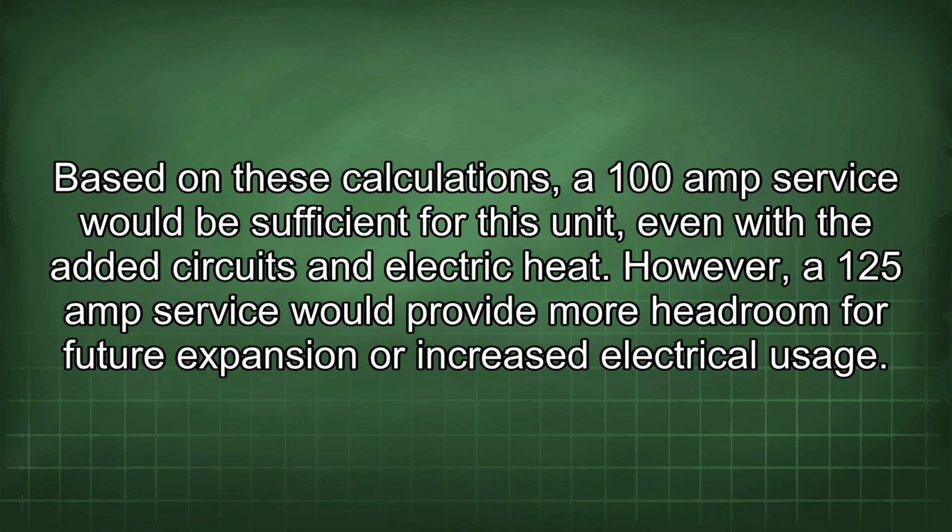Based on these calculations, a 100 amp service would be sufficient for this unit, even with the added circuits and electric heat. However, a 125 amp service would provide more headroom for future expansion or increased electrical usage.